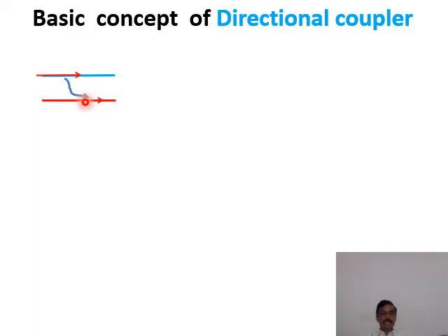This implies that the energy passing through one conductor is coupled to the other conductor. So the induced EMF is taking place because whenever a conductor wire is kept in changing magnetic flux, EMF is induced in that second conductor and the current is also generated. The induced EMF E equals negative d phi by dt, where phi is the magnetic flux.